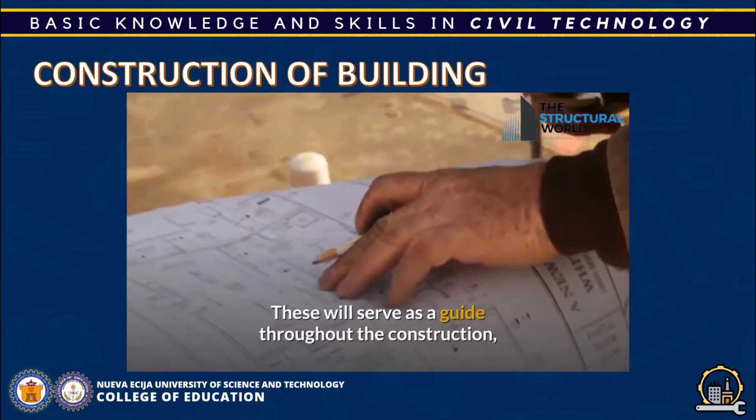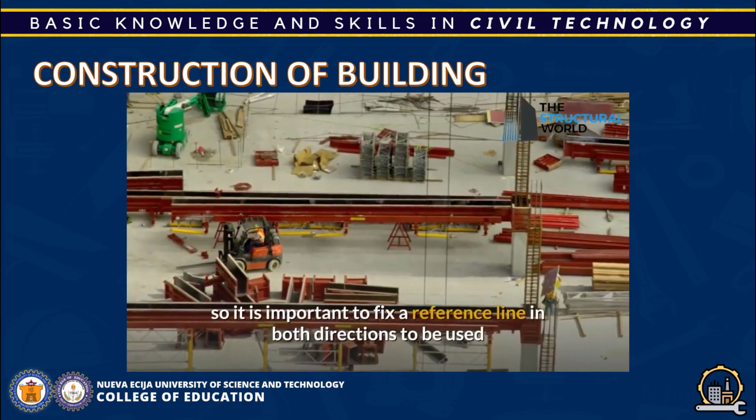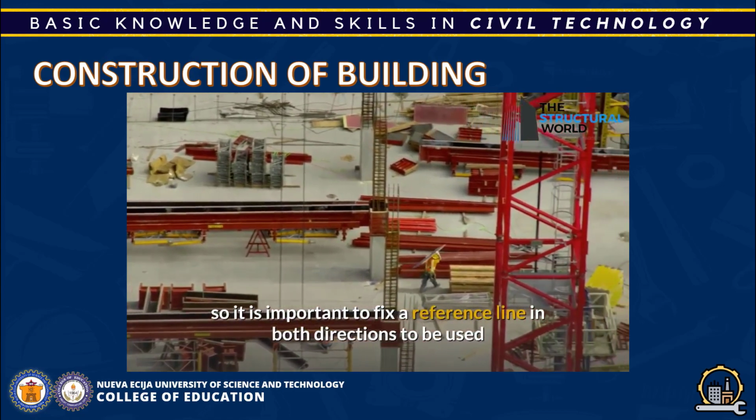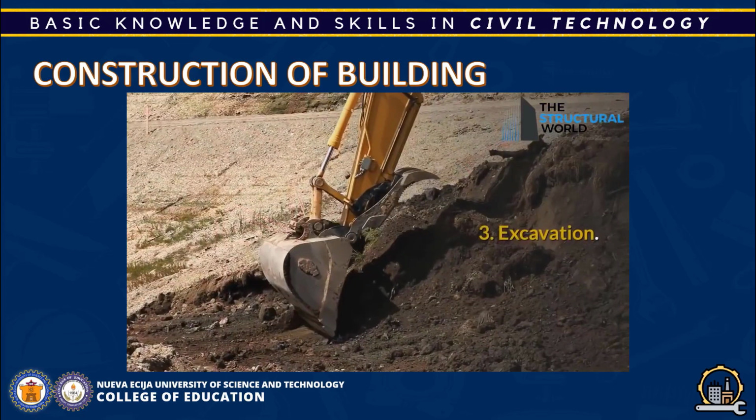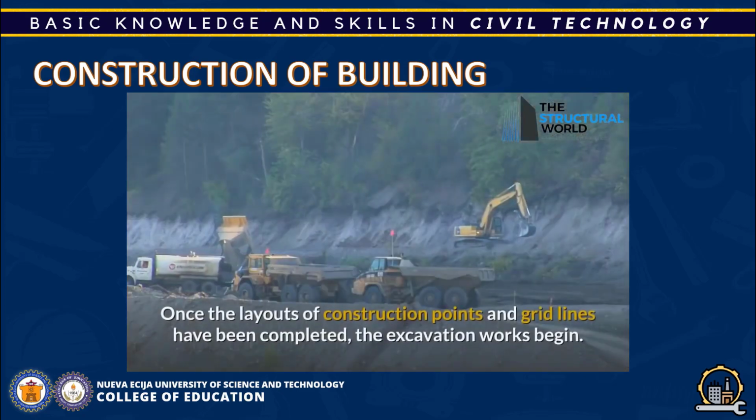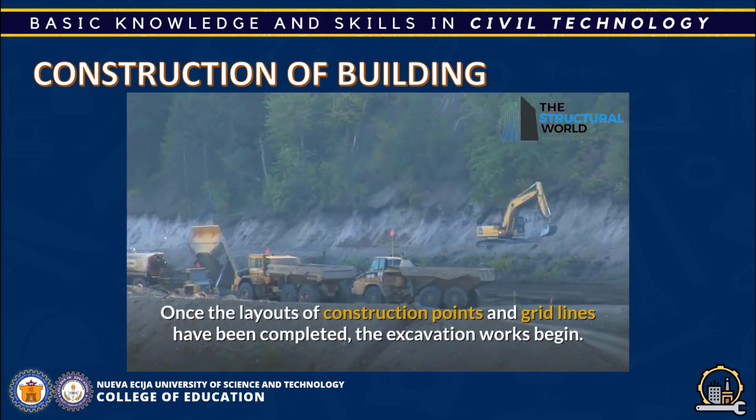These will serve as a guide throughout the construction, so it is important to fix a reference line in both directions to be used once the grids have been placed when needed in the construction. 3. Excavation. Once the layouts of construction points and grid lines have been completed, the excavation works begin.